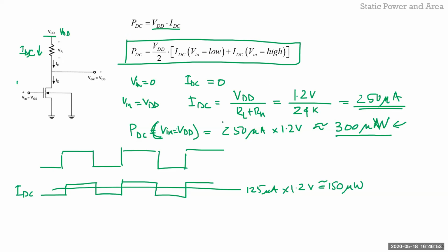So this is not taking into account any capacitor, right? Because if you have a capacitive load now, then every time you charge this, you consume half CL VDD square. Discharge it, you consume this much. So CL VDD square is your power consumed for a total cycle. Okay, so that's all I want to talk about power. It's just that you know that there is power consumed, what's called the static power, even without any capacitive load.